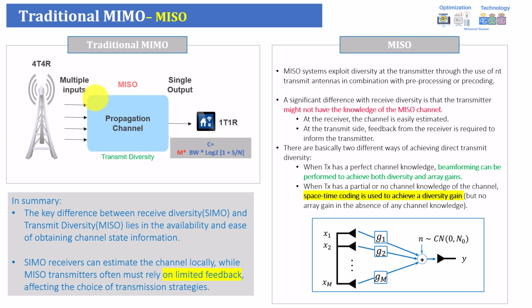What do we mean by space-time coding? Actually, this is an easy one. It means that from these four antennas, it will provide the gain by sending redundant information across different antennas. But again, how will it make sure the data is received? First of all, it will make redundant information. It means data one will be sent, and the same data will be sent through the four transmissions.